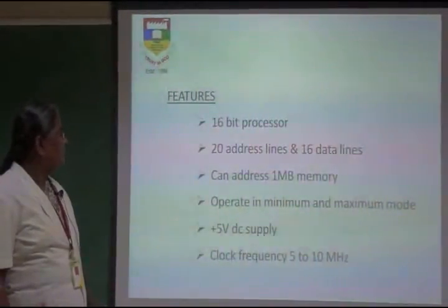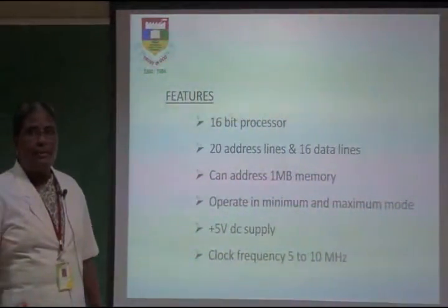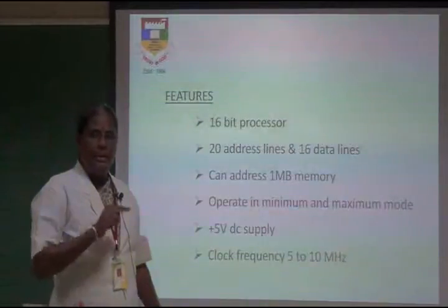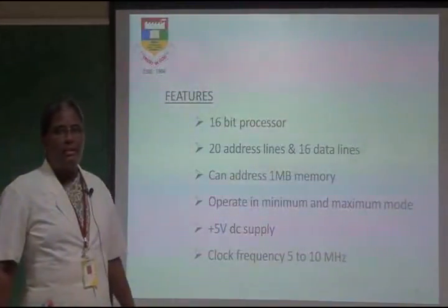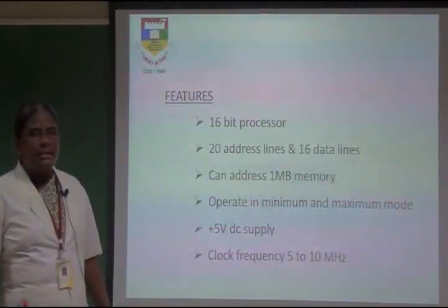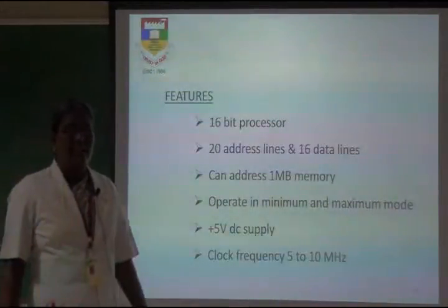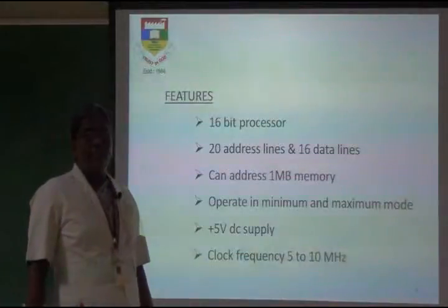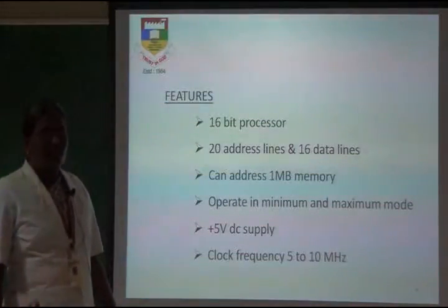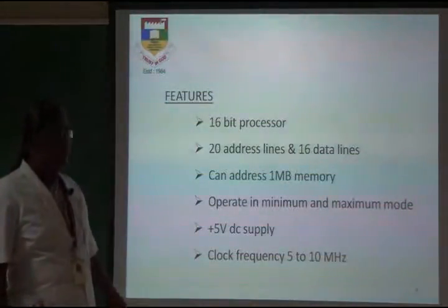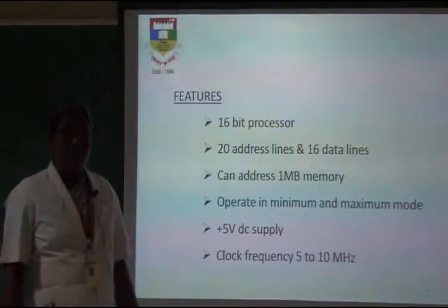First we will see about features. It is a 16-bit processor, so it can process 16-bit data at a time. Then it has 20 address lines, so it can address 1 megabyte of memory at a time, and it can operate in minimum and maximum mode.